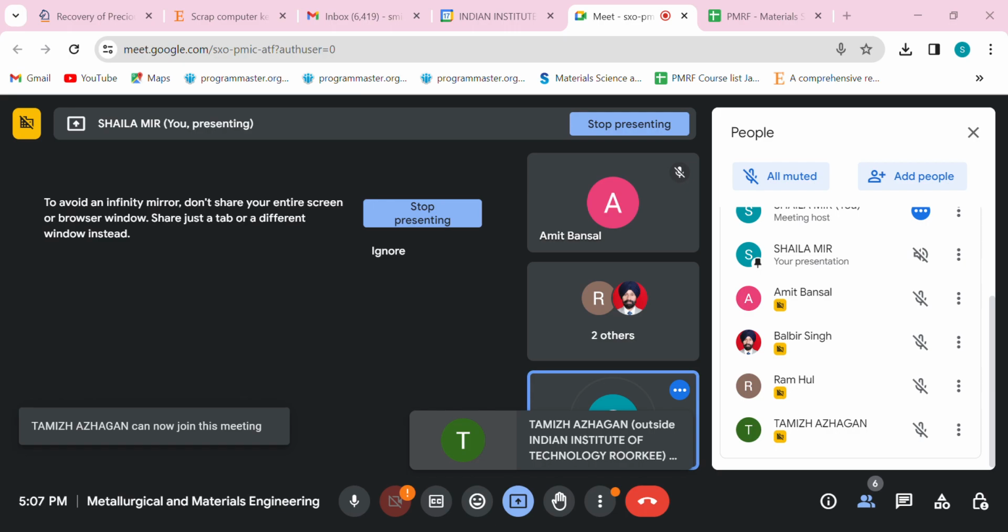Then we have another question that says: hard magnetic materials are suitable for permanent magnets, transformers, solenoids, or none of the above. You know, there are two types of magnets, hard and soft. Hard magnets retain their magnetism and it is very difficult to remove their remnant magnetism. They always have some remnant magnetism. Soft magnets have a very small remanence or coercivity.